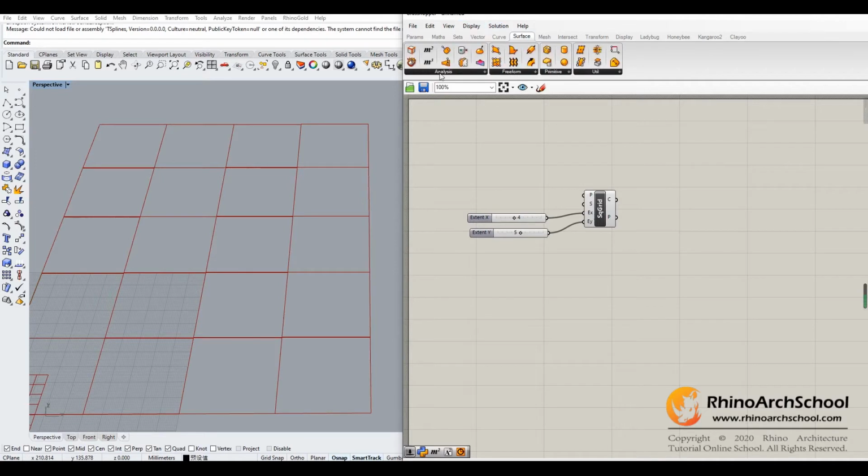Now we need to find the central point of each cell. So go to the surface tool sector, link over here. Now the central point of each cell showed up, and then we need to make the central point move randomly. What kind of direction can you move randomly along?